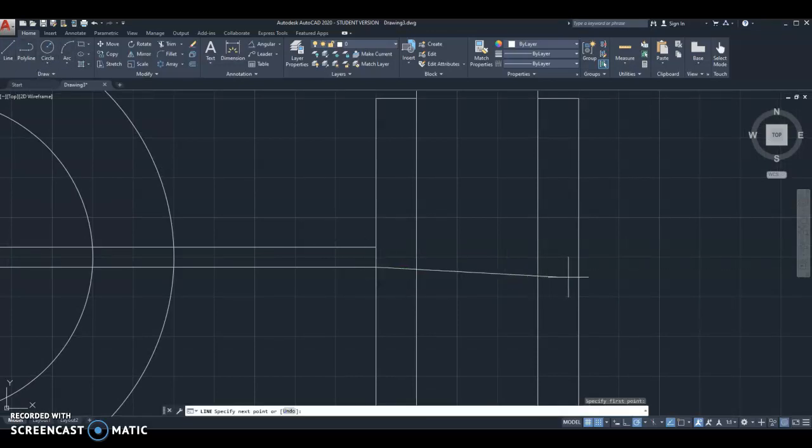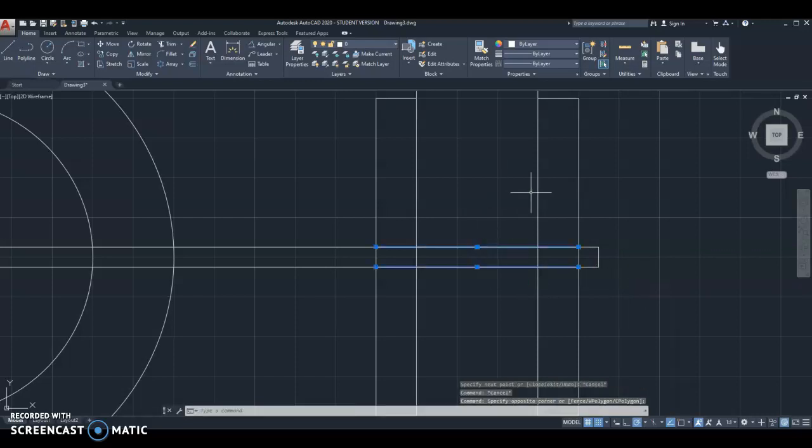So I might just draw a temporary line across there, and then draw another one that comes out. Remember, my snap mode is set to 1/8 of an inch now, so that's 1/8, and that's 1/4. And I can also draw a line across there, and then click, 2 snaps over, and then draw it down. Then I can select those 2 lines and erase them.